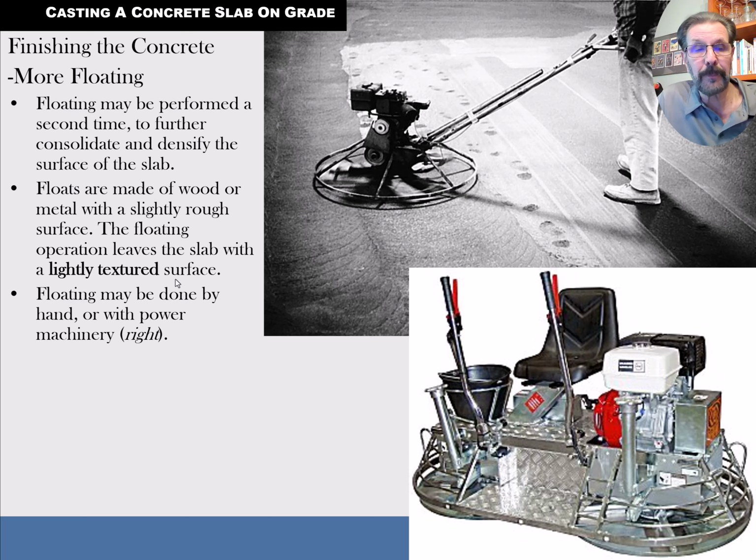And so it's setting up to the point where, if it's getting away from you, you might put what they call float blades on a power trowel to aggressively pull up more. They're going to be much sharper angles, but they're meant to pull up more fines if your finish is getting away from you. But understand, when you use a power trowel for floating, you're already in the troweling stage. And so it's still troweling at this stage. It's not really floating per se.